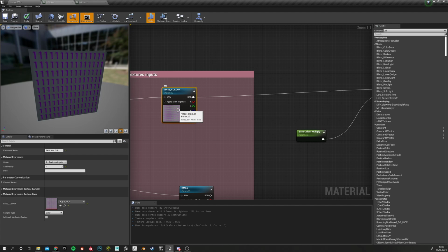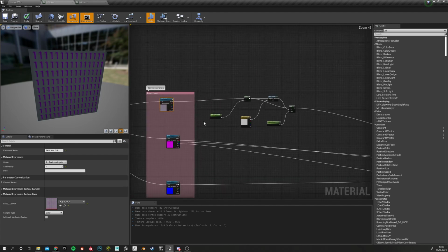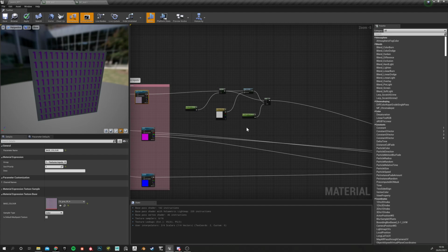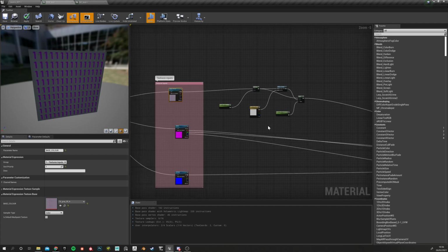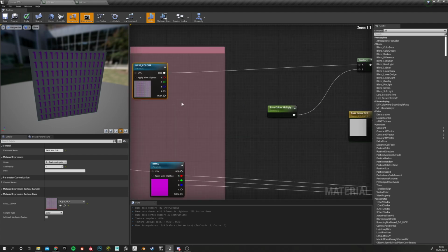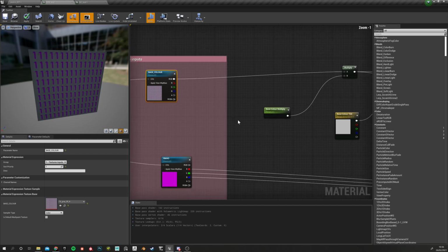And this is quite important, guys, because if you tweak the color for all this and you have two things, where one is metallic and one is not, then you will tweak everything, and you shouldn't have that. So if you want to do that, you have to make sure that you have that here. When you export your material from Substance Painter, make sure you create some sort of mask and then bake it into or embed it into the alpha.